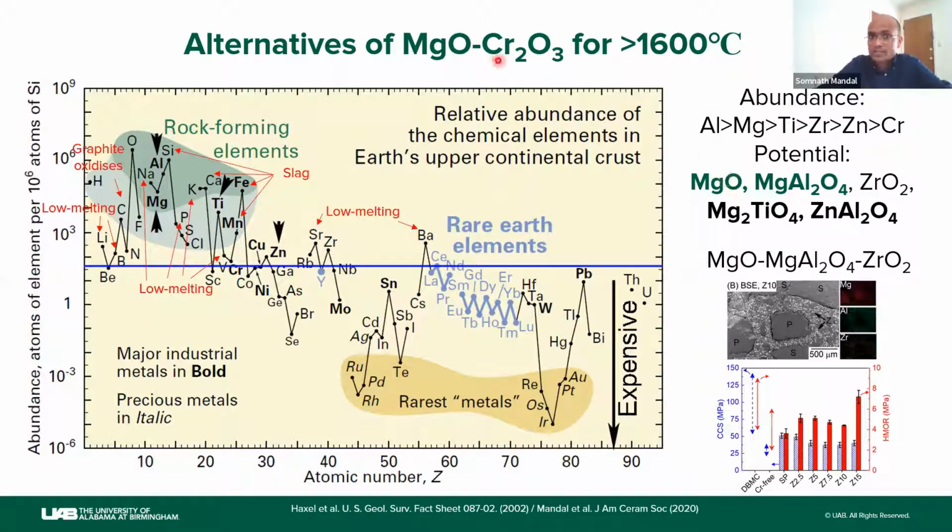By basic I mean MgO based material. So MgO is the main phase, and then you have spinel, and we need a bonding phase. Just like magnesia chrome has a chromite spinel bonding phase, we need something to improve the aggregate matrix bonding, and that will improve the hot MOR and the erosion resistance.